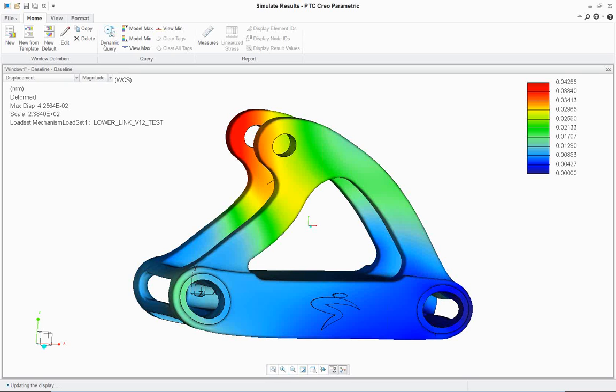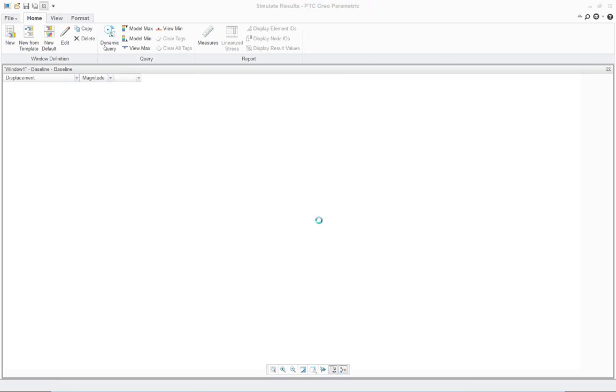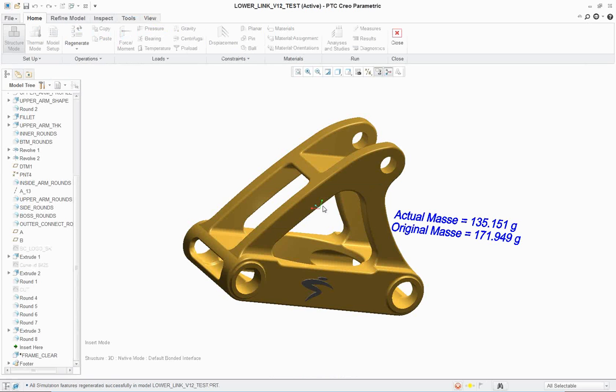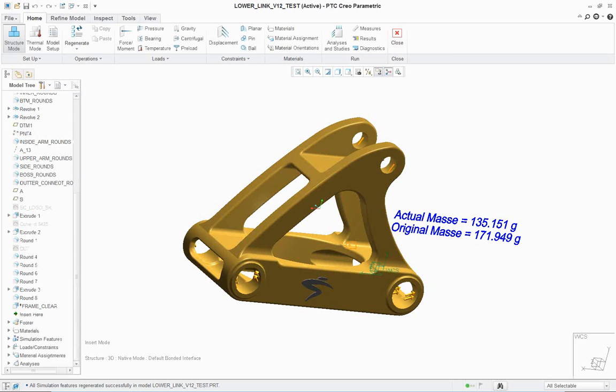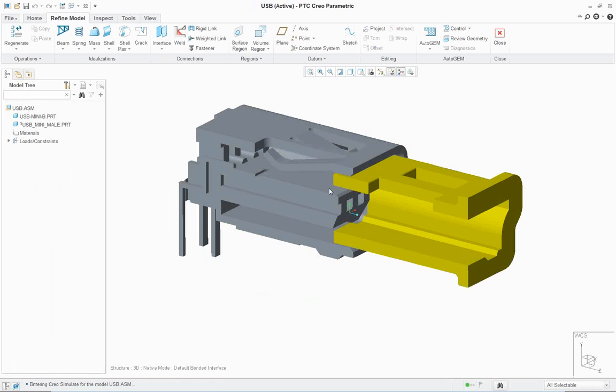Now another question here is, do you have the ability to group the surfaces when trying to define a surface contact? Right now, there is no ability to do that. So basically, you would have to pick all those individual surfaces. But what you can do, and this makes setup so much easier in Simulate, is you can create map keys to do all that work for you.